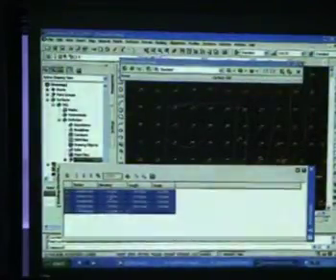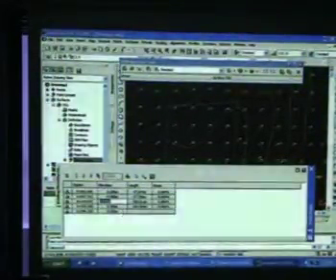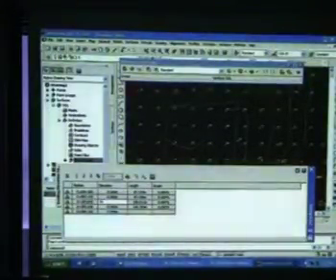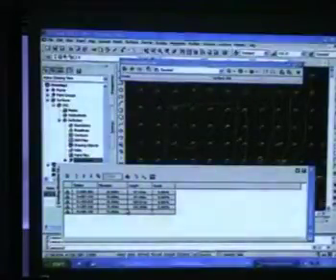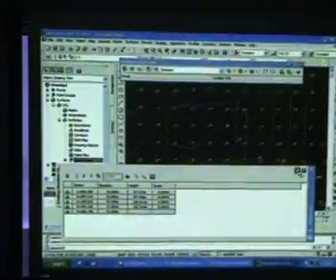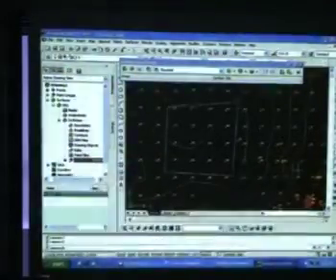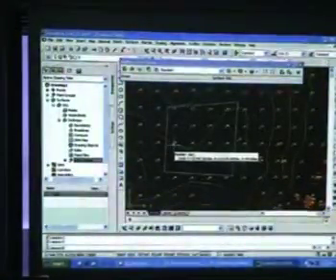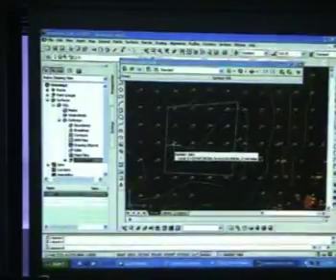To modify the elevation all in one go, you just click anywhere inside the elevation. You see everything else has been grayed out. Then you just type in here. Let's say I type in 35 meters and hit enter, you will find that all the elevations have been switched. Then we click the check mark to dismiss this. So now we've got a feature line at 35 meters in this drawing.